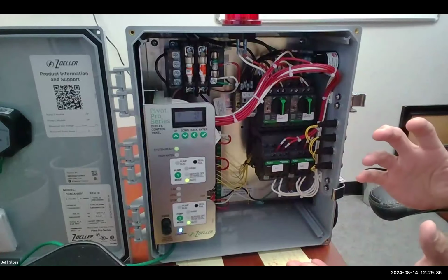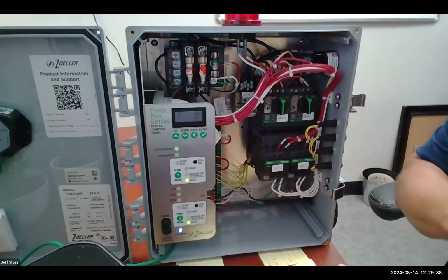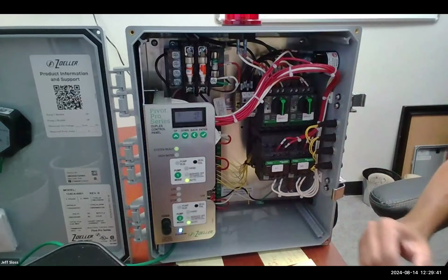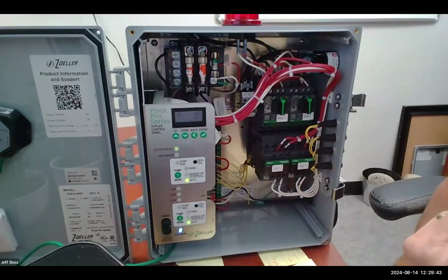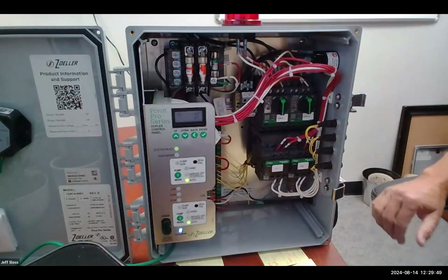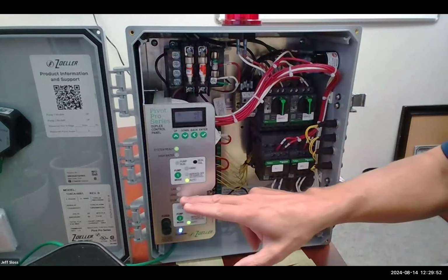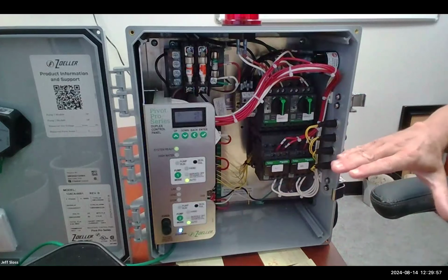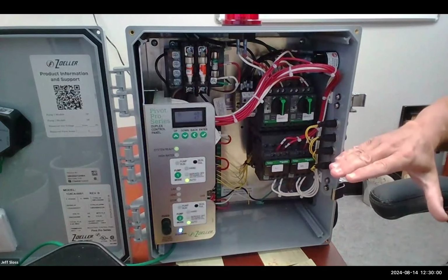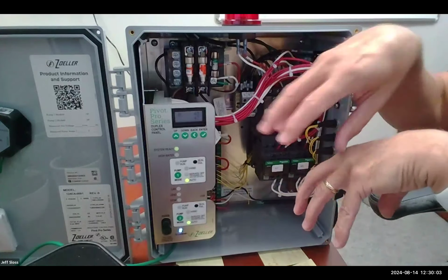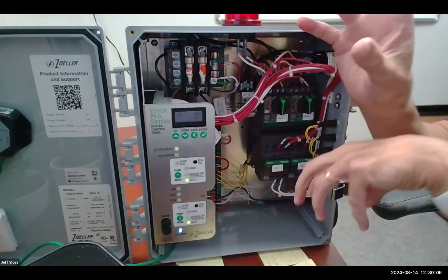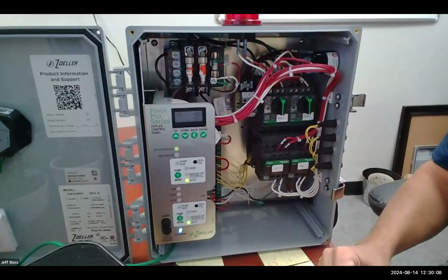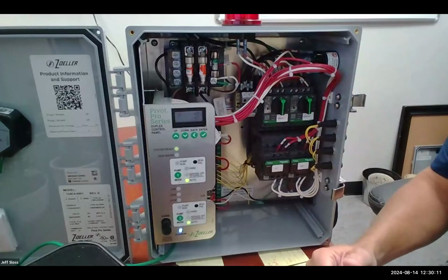That's what a duplex panel does. And old panels do that too. It's the same operation. That's basic operation of a duplex panel. But on an old panel, I usually ask people in the room, I know I won't get an answer necessarily. But if I didn't have a stop float working, if my stop float got stuck, so it stayed down, and the only thing that came on was my lead float. So my stop float got stuck down, my lead float comes up. I ask people in the room, what happens? And they all say, well, a pump turns on and the alarm turns on. And the answer is nothing happens.